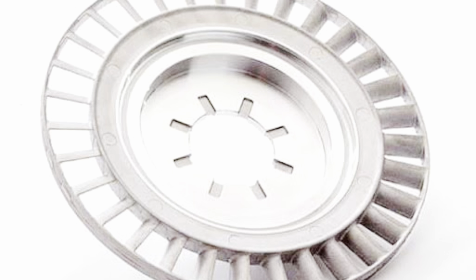With the engine running, transmission fluid is pulled into the pump section and is pushed outward by centrifugal force until it reaches the turbine section, which starts it turning. The fluid continues in a circular motion back towards the center of the turbine, where it enters the stator. If the turbine is moving considerably slower than the pump, the fluid will make contact with the front of the stator fins, which push the stator into the one-way clutch and prevent it from turning.